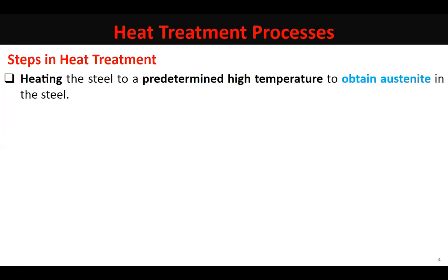Students, I just said that we give heat treatment to change the mechanical properties. And what's the governing principle? If you wish to change the mechanical properties, change the microstructure. And what does microstructure comprise of? Mainly the grain size and the phases existing within that grain size. So the heating step plus the holding step would finalize the type of grain size that would be seen in the microstructure of your material system.